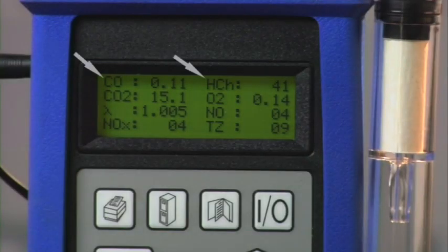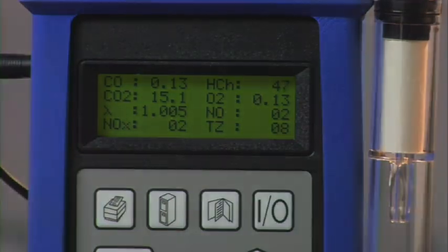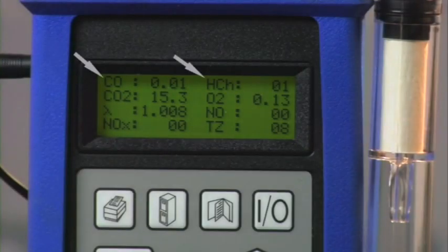As we look at this, we can see the levels of CO dropping down to 11%, and we have HC down to 41% so far. The converter probably isn't totally lit off yet. However, the longer it runs, we should get it to reduce a bit more. Now we can see our levels of CO and HC are now down to a very low level. This converter is working properly and oxidizing the HC and CO.